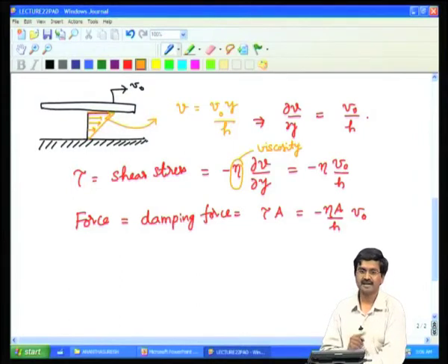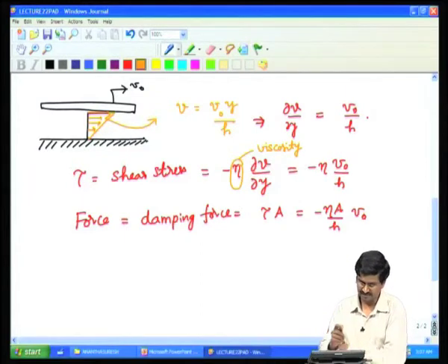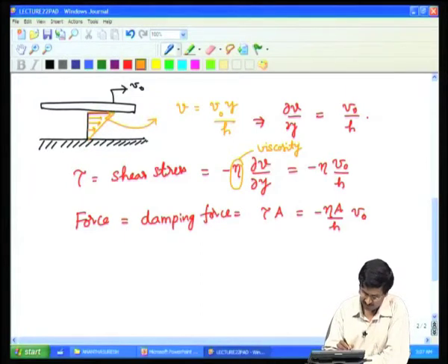There are kinematic and dynamic viscosity, but we are not going into the details, because at micro scale one needs to modify the viscosity based on an assumption called slip flow velocity. We have seen that at the wall the velocity is 0, but that is not necessarily the case in flows through microfluidic channels. There will be a slip between the wall and the fluid particles.